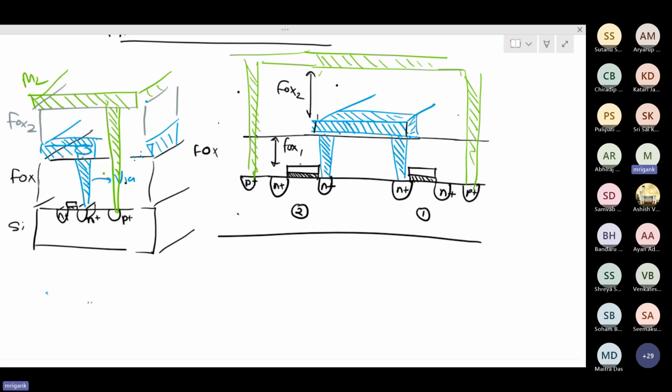I think I will give you some more slides in which more realistic pictures will be given, which will be good for the visualization. But ultimately, you understand how the connectivities are being formed. If you look at the top of any metal layer, like metal 2 layer, if you are trying to visualize how the pattern will come, it is a pretty complex pattern based on the way you have defined the connectivities. You have etching, you will have some parts having the metal, some parts not having the metal. So it will be a pretty complex pattern, nanoscale dimensions, which will be defining the connectivity between different layers.